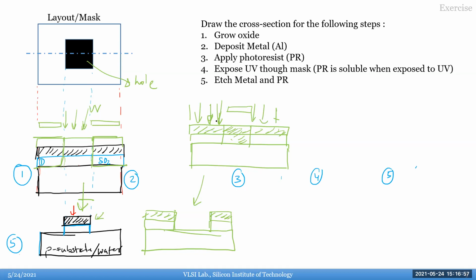So this is really a processing thing. They decide which one to use. I'm not a processing expert, so I don't know how they decide, but I'm just telling you there are different ways you can do negative masking or negative photoresist. Here we said wherever it is exposed, keep that. If you did a negative photoresist, then it will just remove this away. And even with this mask, you'd still get our original, where you have the oxide and this is your metal here. Okay, did that make sense?